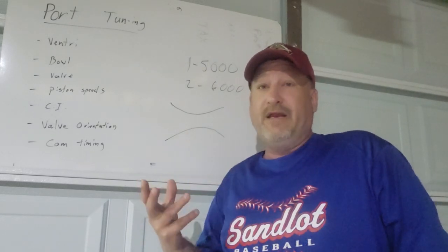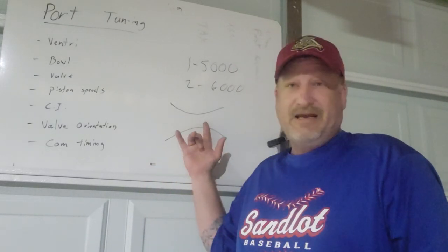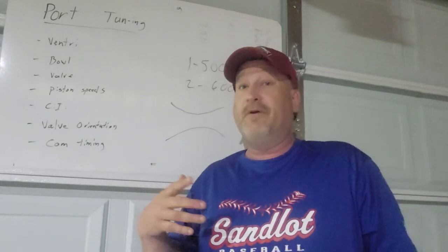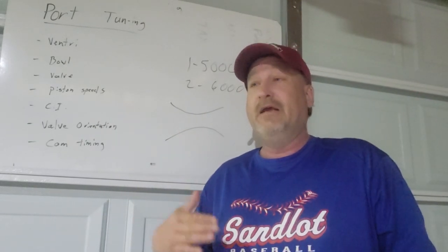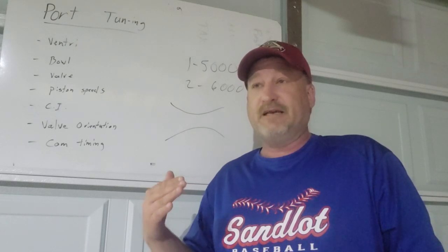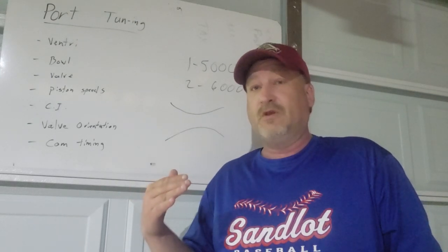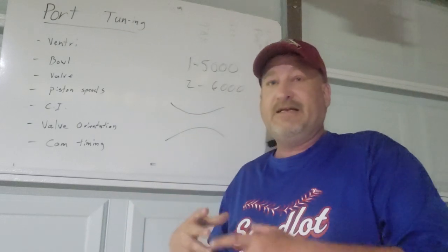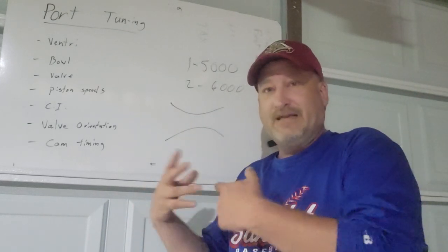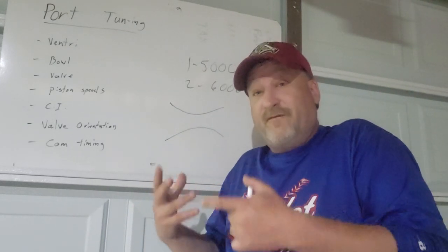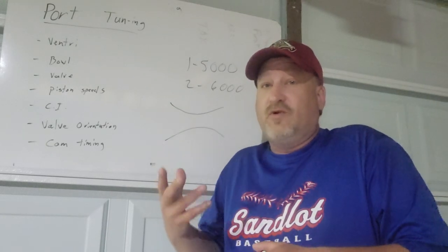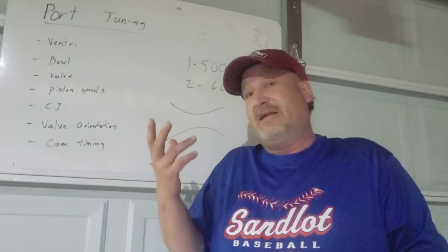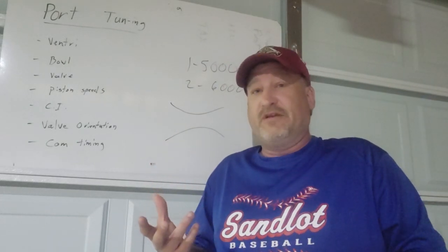Now, tuning is not just inside of the intake system itself. It actually occurs from the piston travel also, because again, as the piston is leaving top dead center, the speed of the piston and the volume, the area of the actual bore of the cylinder, dictates when the intake port is receiving the most amount of vacuum. Again, the piston normally is extracting the most amount of vacuum at approximately 50% of the travel within the cylinder.